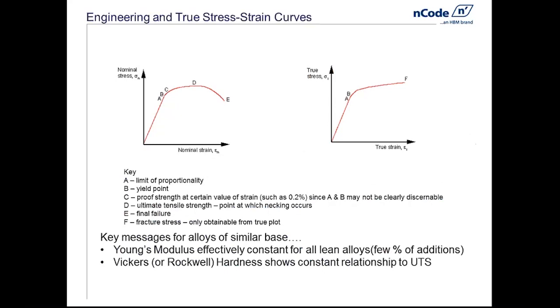Let's go back to a more familiar field from the engineer's point of view. What does this show up like if you deform it and measure the deformation properly, as opposed to just squeezing it and looking for the kinks? On the left, I have the engineering stress-strain curve, and you can see that in the region from the origin up to the letter A, we can pull it, and it will deform up and down that, and it can return to zero when you take the load off. But if we get past B, it will deform permanently. Very often, and this has been my own experience of test work, you cannot determine a clear yield point.